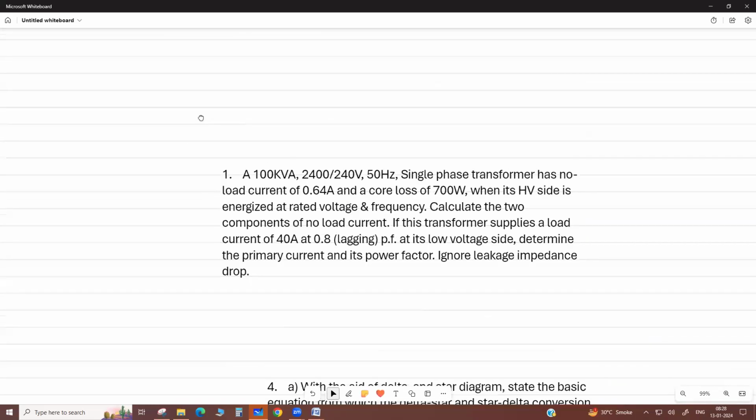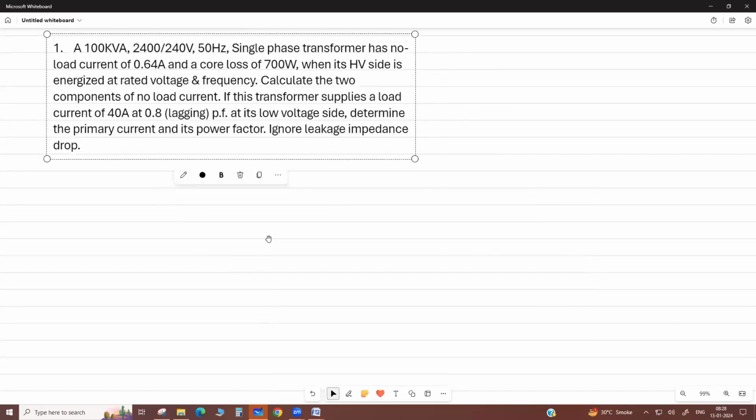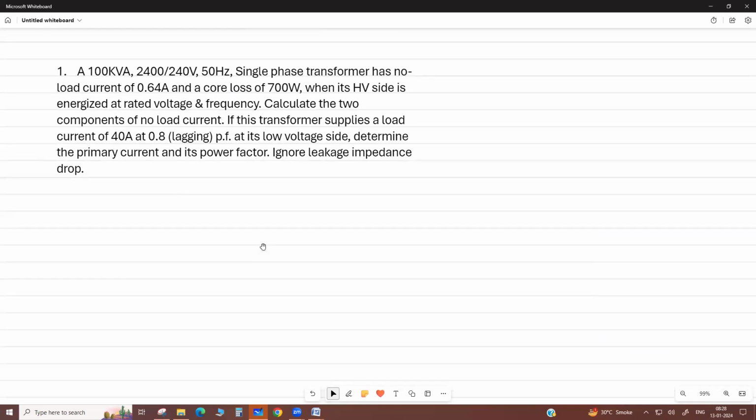Okay. जरा start कीजिए. Okay. Maybe they ask. It was already needed. See, turn ratio rating is given. So what is the no load current? Single phase no load current is given. Core losses. Core losses means no load input. So actually here no load power factor is not given. No load current is given, but cos phi not given. So you can calculate from no load input.